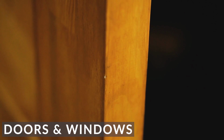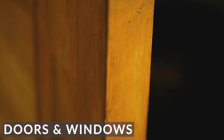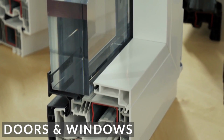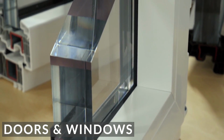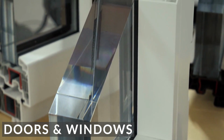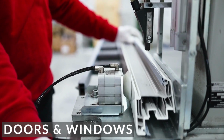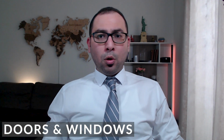Then you have items related to doors and windows, so the types of wood specified for the doors and the fire rating of the doors, ironmongery for the doors, and also aluminium sections and the glazing for the windows and curtain walls, type of powder coating for the windows and curtain walls. So these are the items or the elements that can impact the cost of doors and windows.